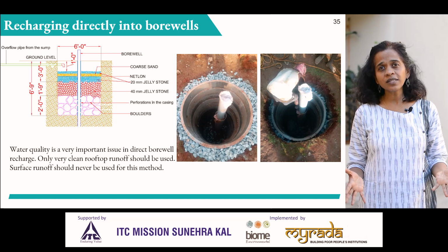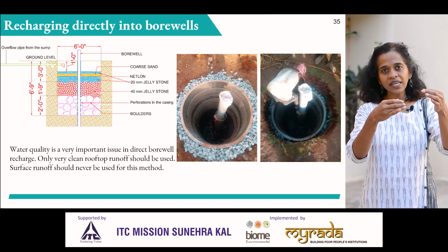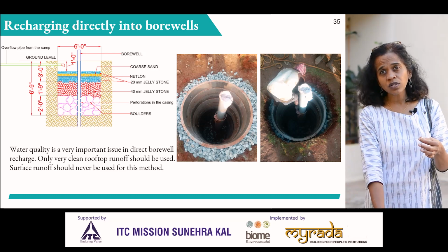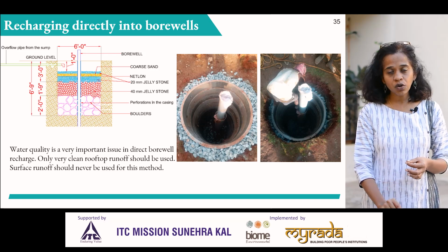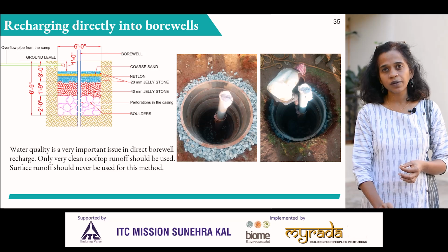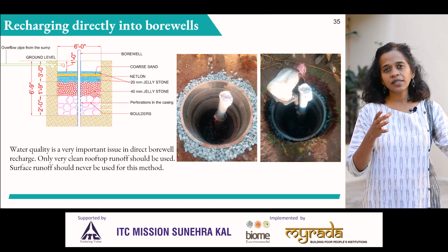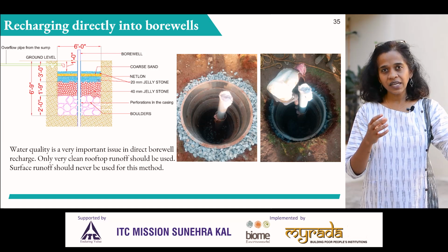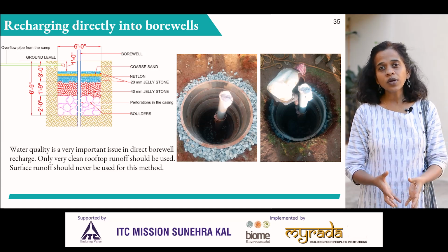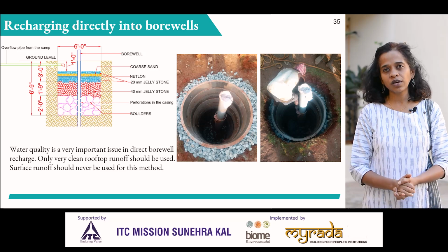Why do we do all this? Because the water that you put in is the water that directly goes deep into the deep aquifer. There is no capacity in the rock to further filter this water. So you have to make sure that the water you put into the borewell has no contaminants in it, because the rock has no capacity to filter this water further.